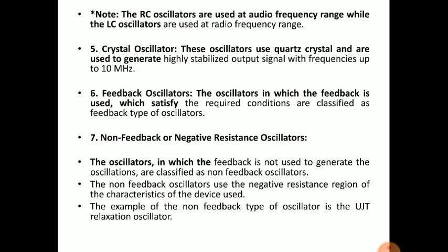So, depending on the components we use to produce the oscillation in the tank circuit, if it is an RC, the output frequency will be in the audio frequency range, that is up to 20 kilohertz. But if you use LC, inductor and capacitor oscillators, then we will get the frequency in the radio frequency range, that is greater than 20 kilohertz.